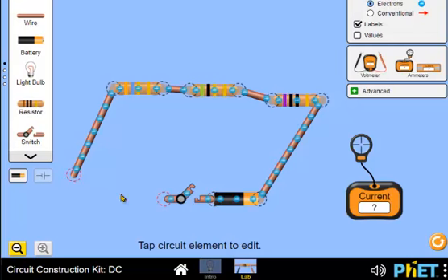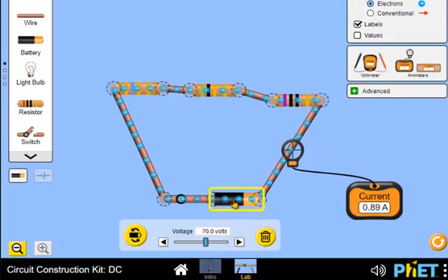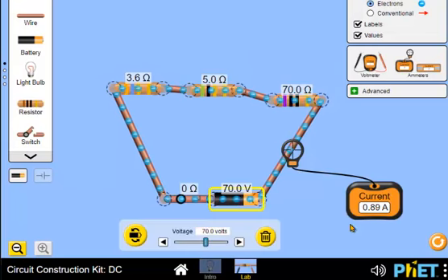I'm going to put a switch in here. And I'm going to close the switch here. There we go. And I'm going to put the ammeter here. And the thing is, this particular circuit applet, by the way, I want to show values. Did I show them earlier? I forgot. Anyway, this particular applet doesn't let me measure resistances. They only give me a voltmeter and an ammeter. They don't give me an ohmmeter. So what I'm going to do is increase the battery voltage here until I get a nice 1 amp, and then I'm going to use Ohm's law.